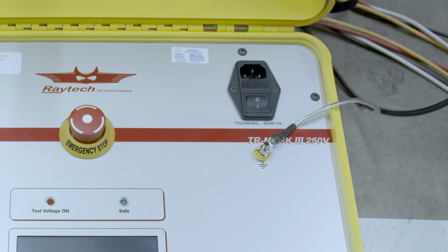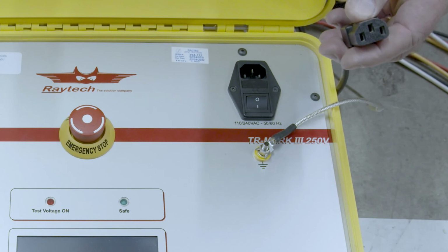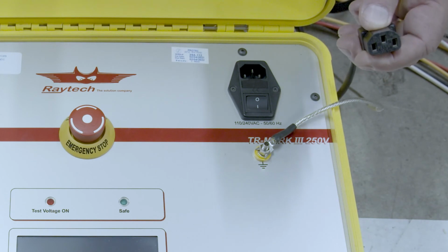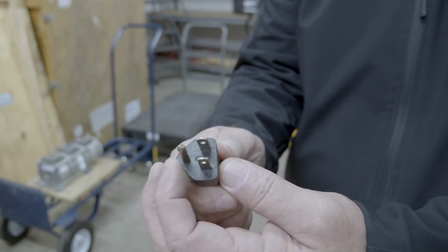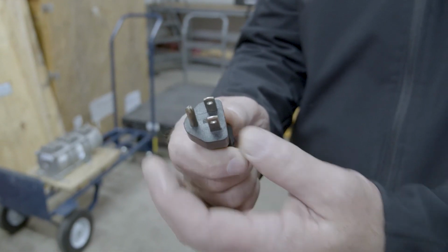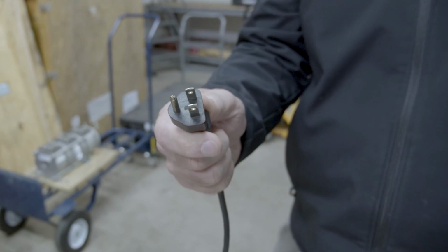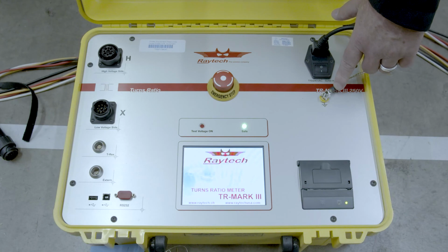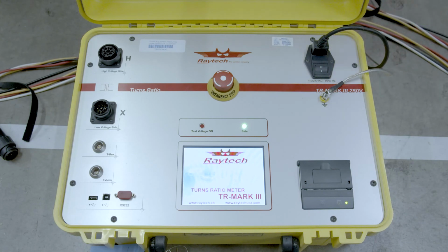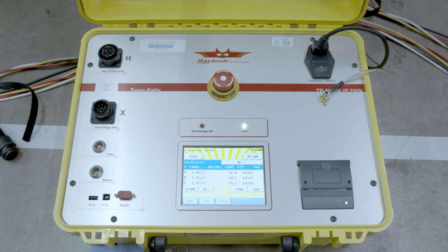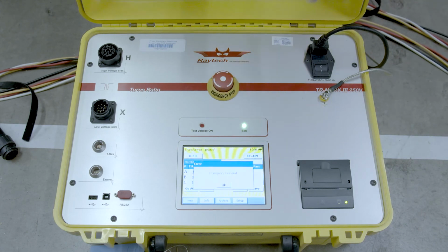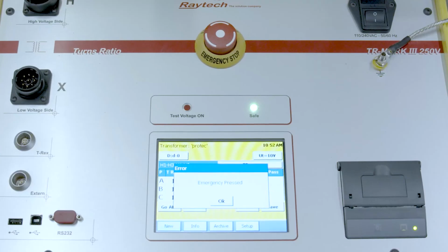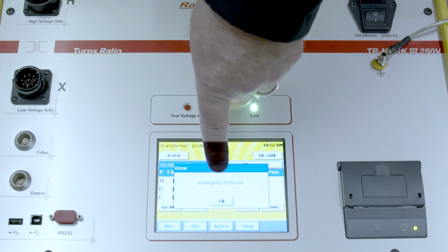We also have a ground that we get through the power cord to the instrument. It supplies a third prong, which is the ground connection to the instrument, and this allows us to have the safety feature as well as a reference for the instrument and the measurements that are being made. Additionally, we have an emergency stop button. If you just simply press that, if anything were to be wrong, then you can twist and release it. You'll notice the display shows that the emergency stop button was pressed, and it would interrupt the output.